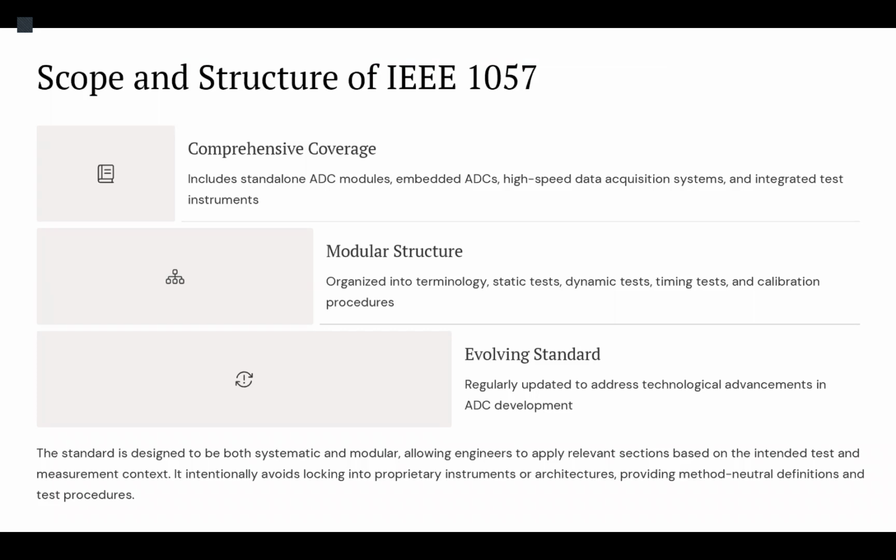This modularity allows engineers to select and apply only the relevant parts of the standard. For example, if the goal is to verify offset and linearity, one may only apply the static tests. But if the focus is on spectral performance and high-speed ADCs, then the dynamic testing section is applied to our procedures.